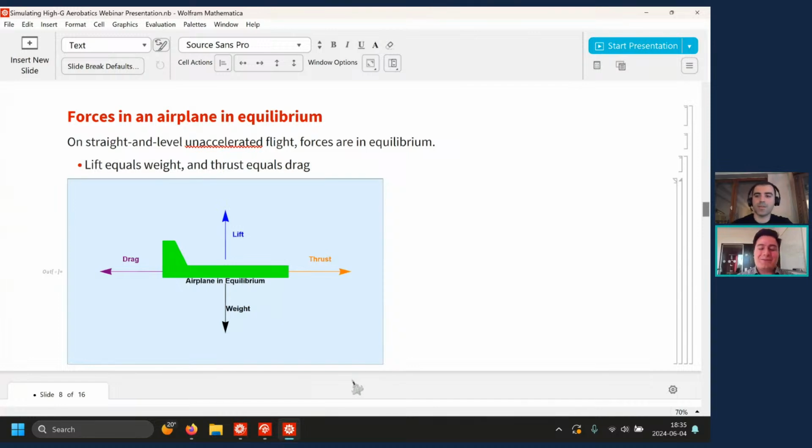Of course, coming back, does it also allow for low Reynolds number airfoils? Yes, of course, it depends. You cannot really get into the tricky regimes of Reynolds numbers. If you want to capture the transition and all this stuff, this model is not for that. It might give you some insights, but you need to know your limitations.